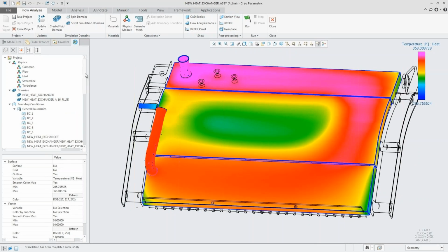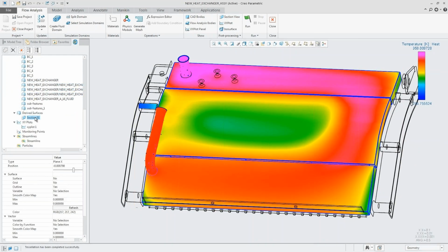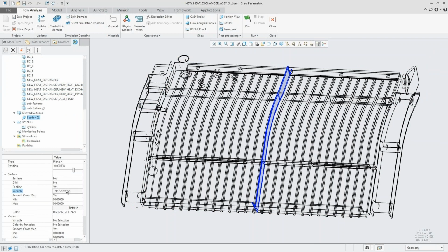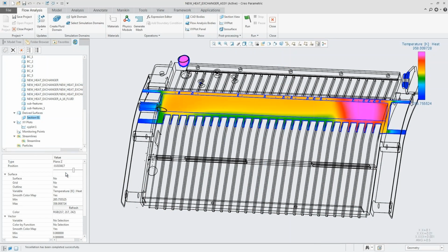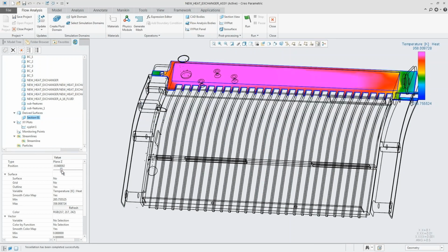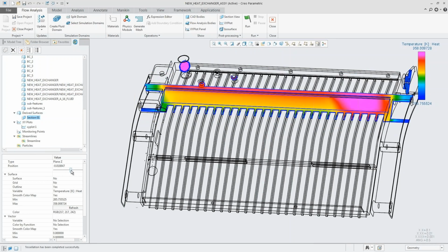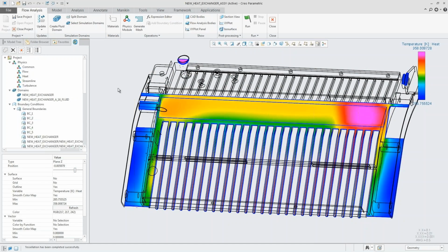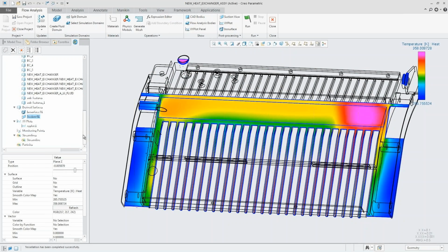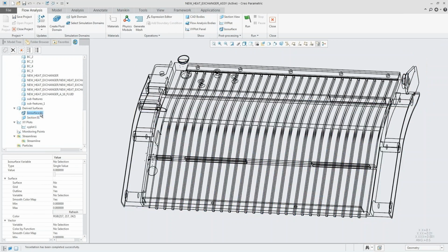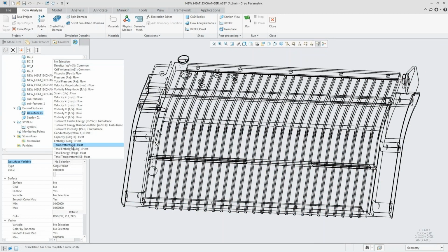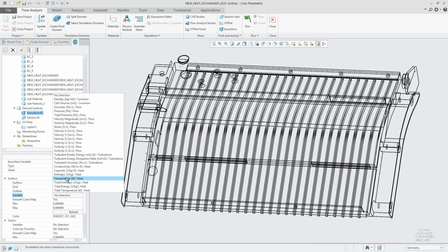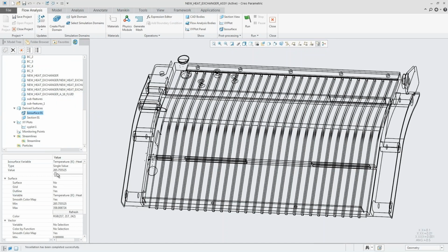And one of the other useful tools I have here is the ability to take section views of the results. So say we want to take a look at some of the temperature values inside the model, well, we can move that to the X-plane and the Y and the Z, really wherever you want to look. On top of that, we also have another tool at our disposal for looking for specific values throughout this simulation. If I want to do that, first we have a slider bar that we can essentially move from a minimum to a maximum and see where those values are in the model.